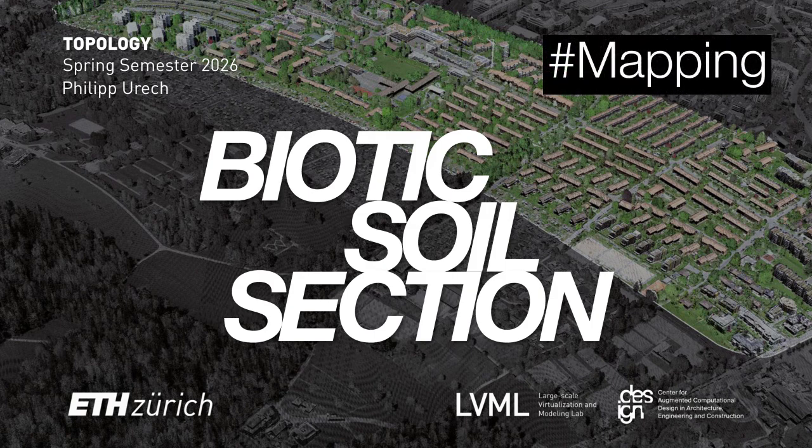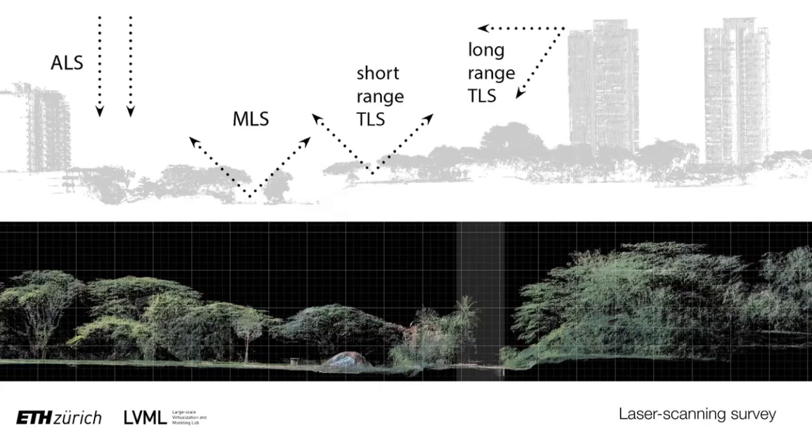So let's start with different ways of using a laser scanner. For instance, an aerial laser scanner is a device that is set on a plane, and then this active sensor measures vertically. You can also put a laser scanner on a car, then it's mobile scanning.